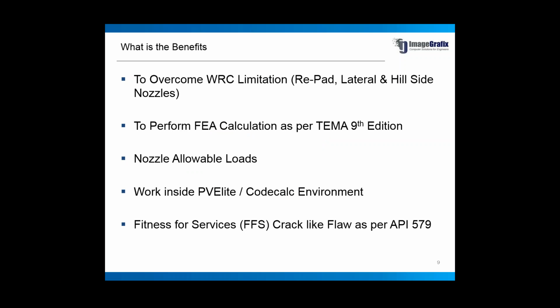And you work inside the PVElite and CodeCalc environment. You're not trying to learn a new product. You're not trying to learn how to model in FEA, how to do the FEA analysis, the methodologies, everything. It is not mandatory to learn all these things. You're just in the same PVElite and CodeCalc environment. All the input which you have done has been done. You're just shifting the analysis method from TEMA to FEA. Both are TEMA only, but FEA is the 9th edition of TEMA, of course.